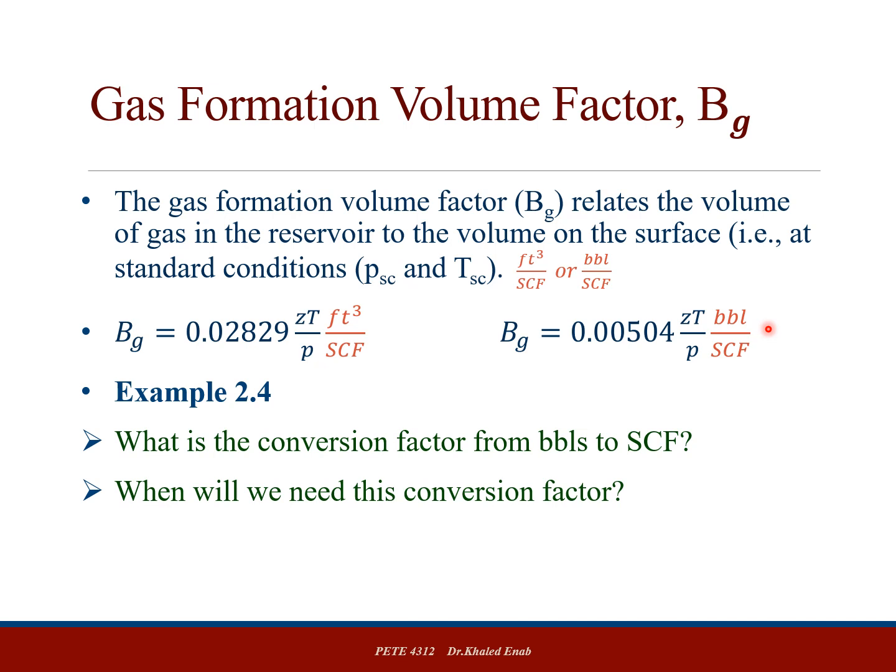Does this make sense? Yes. But if you think about it, I have only 50 cubic feet volume in the ground and I produced more. So if you ignore the pressure and temperature, and you ignore the ideal gas behavior on the surface and the real gas behavior in the reservoir, your whole problem would be messed up because you produced a volume which exceeds the available volume in the reservoir.